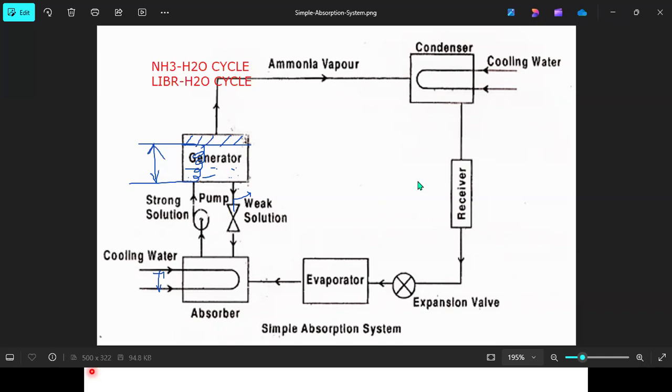All right guys. Okay, that's it. So this is one type of vapor absorption cycle itself, meant to be the ammonia water cycle. Normally ammonia based VAR cycles are used for cold room applications. For example, meat storage factories, dairy processing units, and especially these kinds of areas, they will be using these ammonia based water absorption refrigeration cycles.